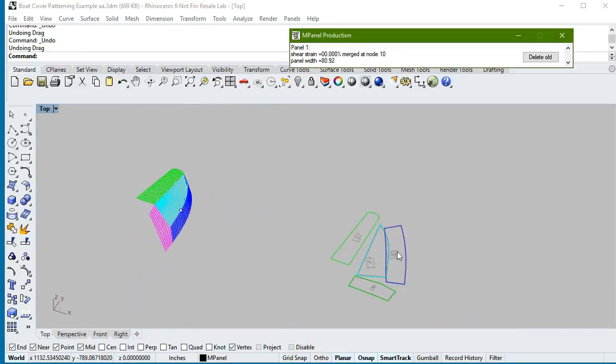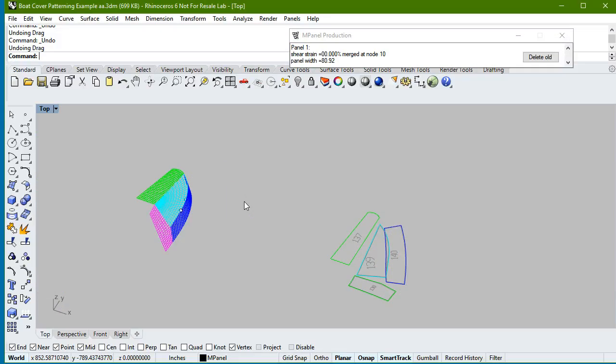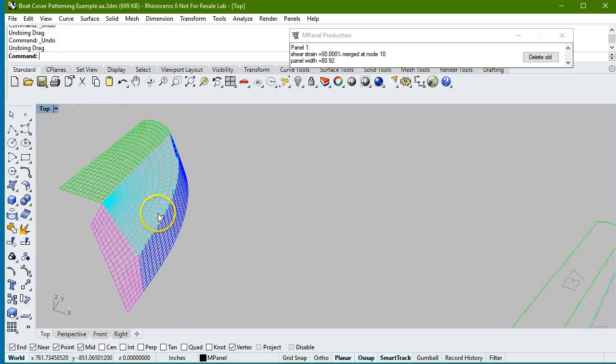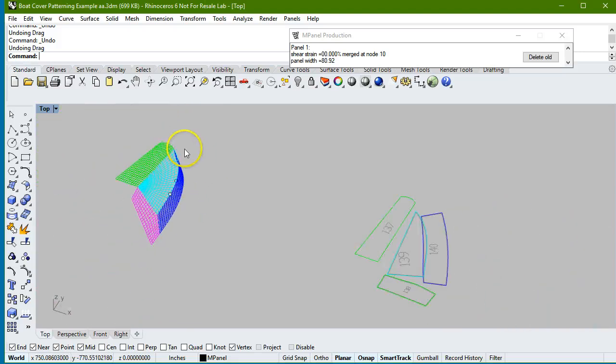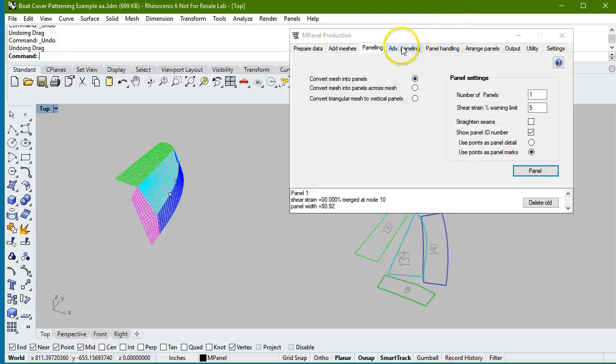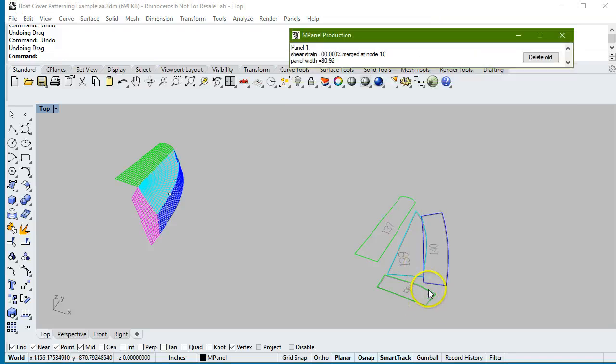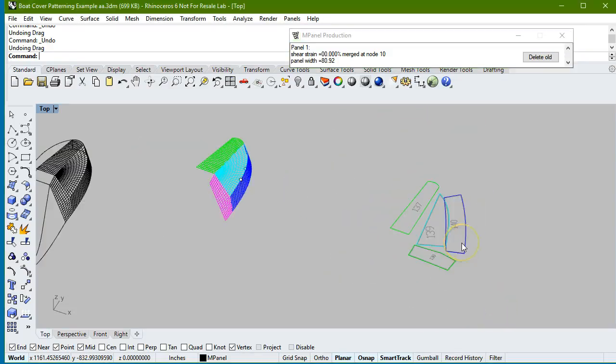same marks inside them. So just in summary, in most cases we don't need to add points to establish mark points across from one panel to another, because the program can do that automatically during the panel handling by specifying the number of marks. For joining 2 adjacent panels, we have a procedure which puts marks in the places on the adjacent panels where a panel join occurs. And for those rare occasions where we do actually need additional marks, we can draw them in as points.